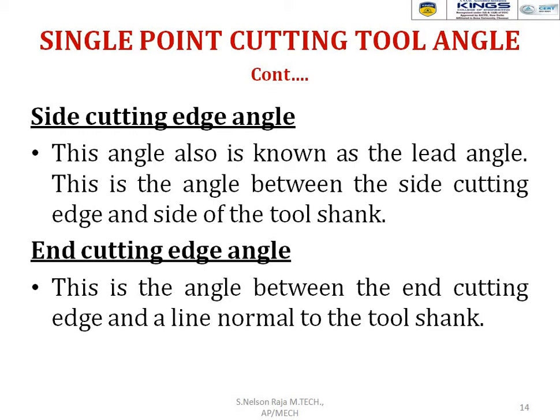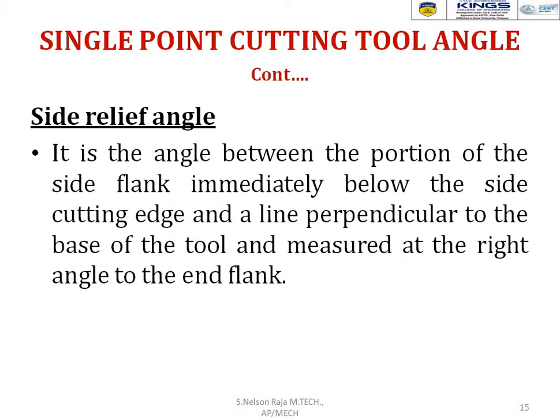And the second one, end cutting edge angle. This is the angle between the end cutting edge and the line normal to the tool shank. It is called the end cutting edge angle. And the third one, side relief angle.